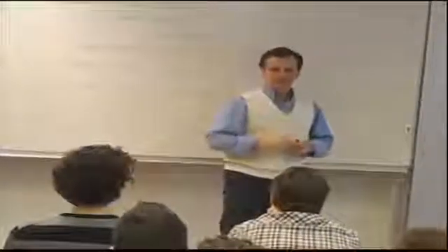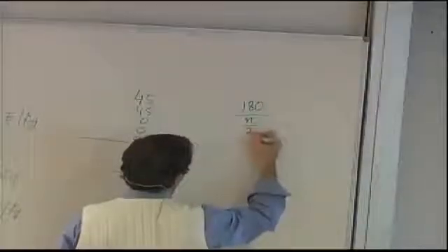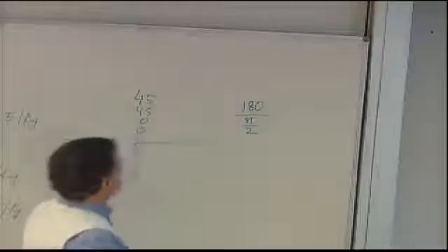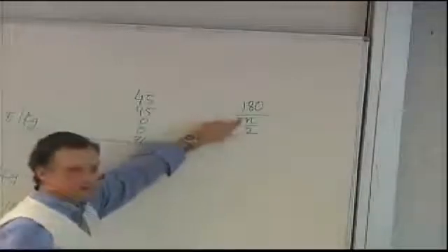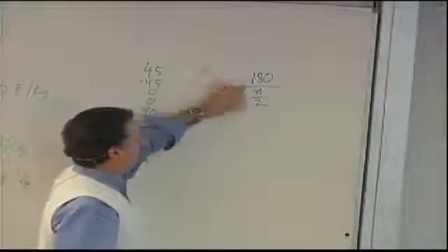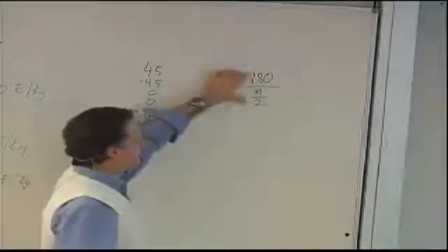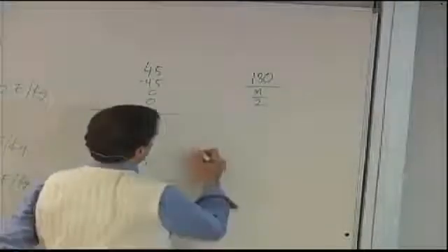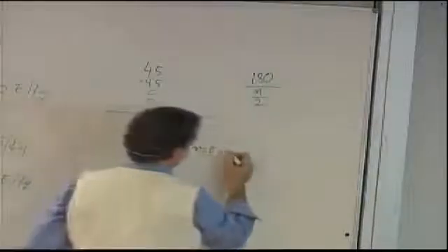But instead of having an infinite number of fibers distributed every degree, you can do it at certain intervals of degrees. So the quick way to do this is you take 180 and divide by n divided by 2. So that if you have n layers, you divide it by 2, you get 4. No, you don't get 4. I haven't told you what n is. The example in my mind is 8, but don't worry about it. If you have n layers, divide by 2, and then you divide that into 180. That tells you that you need fibers every so many degrees. So if the example says n equals 8, 8 divided by 2 is 4, 180 divided by 4 is 45.